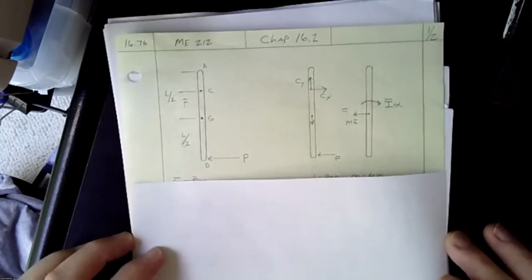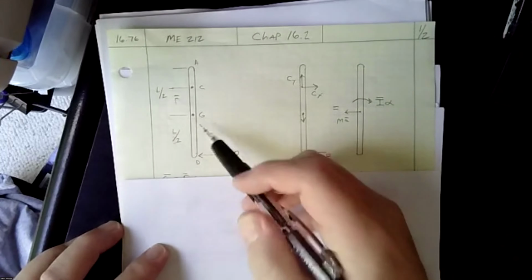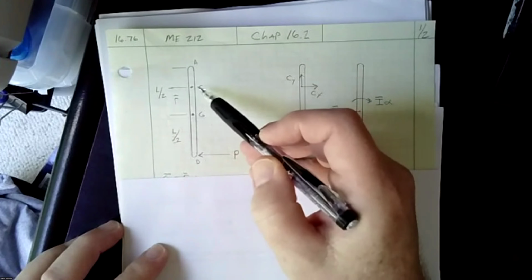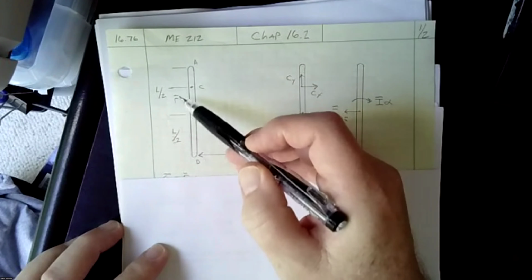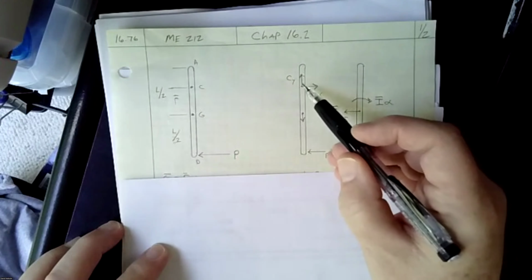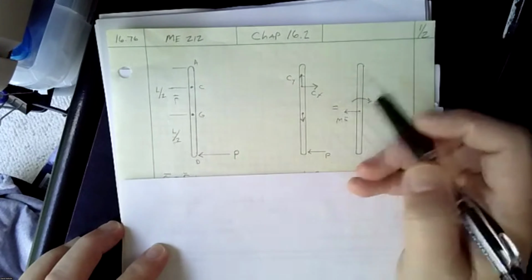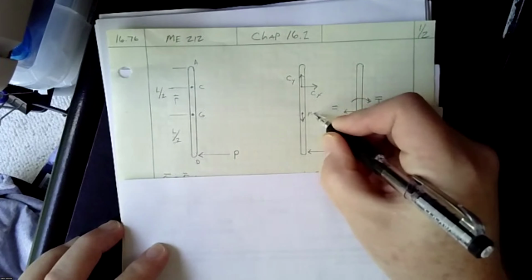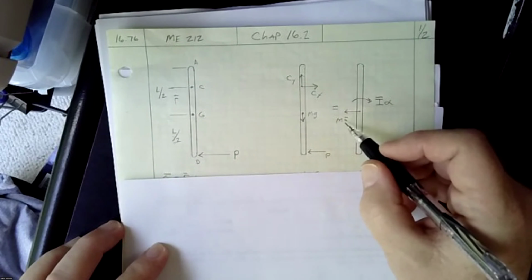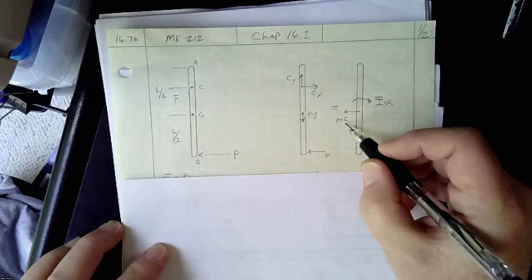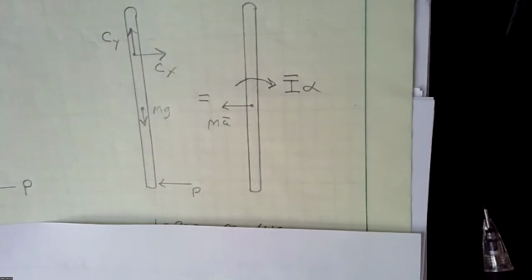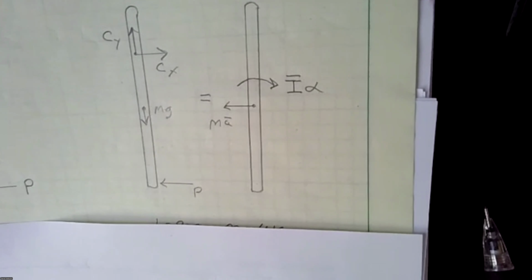Here's what it should look like. So I have L over 2, L over 2. There's R bar from point C. R bar is just, again, our perpendicular distance that we define. The reaction Cy, Cx, and this here being our mg. And then we have the mass times acceleration A. Sorry, it's a little harder to see. That's an A. And then I alpha going the other way.